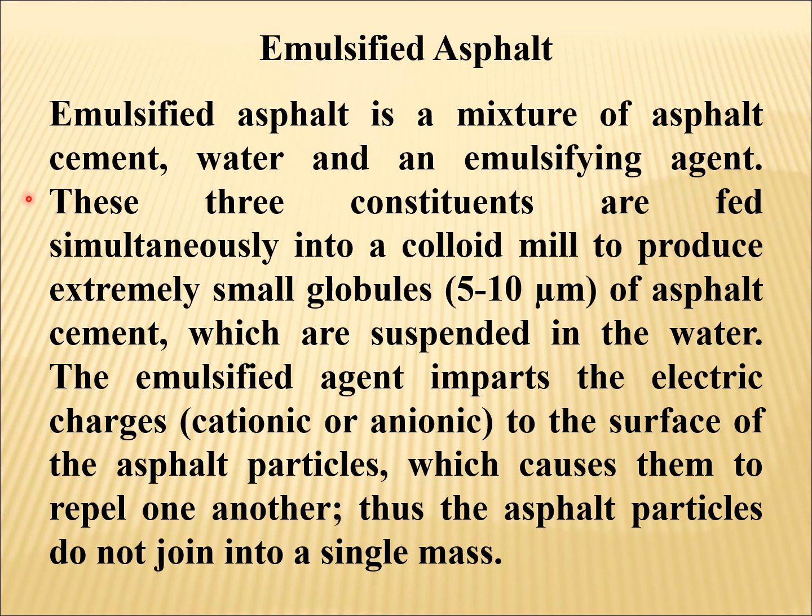These three constituents are fed simultaneously into a colloid mill to produce extremely small globules, 5 to 10 micrometers, of asphalt cement, which are suspended in water. The emulsifying agent imparts electric charges, cationic or anionic, to the surface of the asphalt particles, which causes them to repel one another. Thus, the asphalt particles do not join into a single mass.